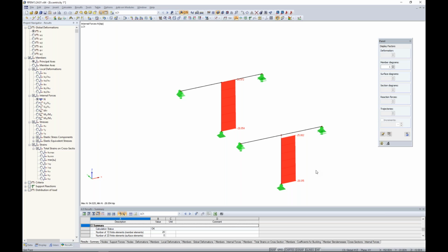difference. So my point being here is that we perhaps have a huge model. We've applied all these eccentricities for our columns to drop that down to the bottom of the beams framing in above it, with very, very little influence on our results, which really doesn't make it worthwhile. So maybe not detrimental here in terms of additional forces, but really no difference. So there's no reason to apply these offsets in these situations.